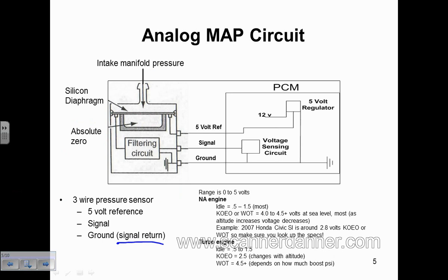And I'm giving you some voltage readings on here, common voltage readings you're looking for. As with other sensors, our range is 0 to 5 volts. But do we want to see 0 or 5 on any sensor that uses a 5-volt ref? No, you see 5, you got an open, right? You see 0, you got a short. Although on some designs we can have 0 and have an open too, correct? Depends on that internal resistor we talked about.